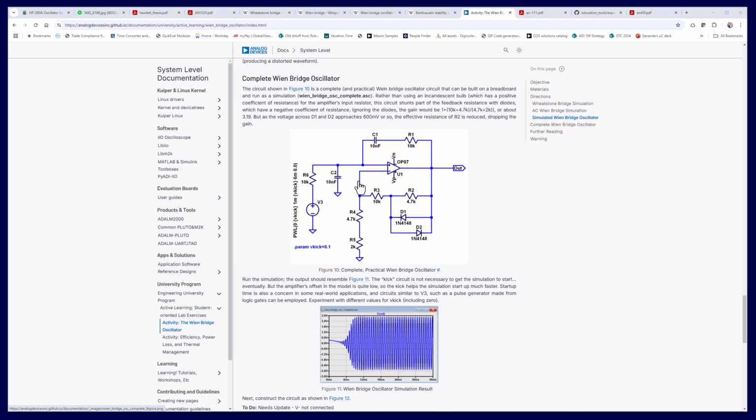The output of the amplifier feeds this Wien Bridge network, and the center of the network goes to the amplifier's non-inverting input. I've also set up the amplifier with about 10, 15-ish K in the feedback network, and about 5-ish K in the input resistance.